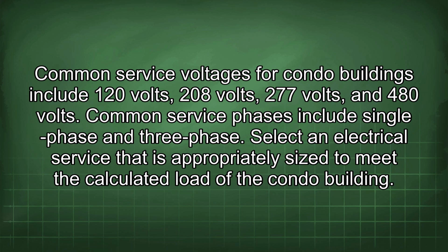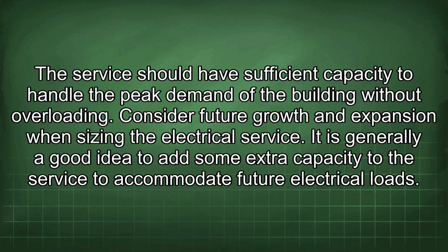Select an electrical service that is appropriately sized to meet the calculated load of the condo building. The service should have sufficient capacity to handle the peak demand of the building without overloading. Consider future growth and expansion when sizing the electrical service. It is generally a good idea to add some extra capacity to the service to accommodate future electrical loads.